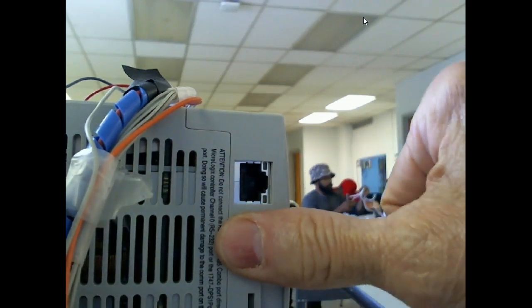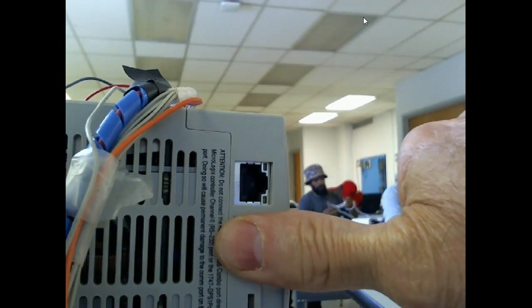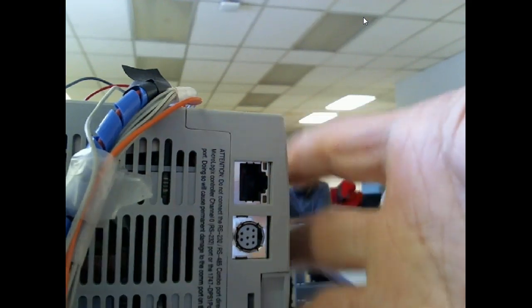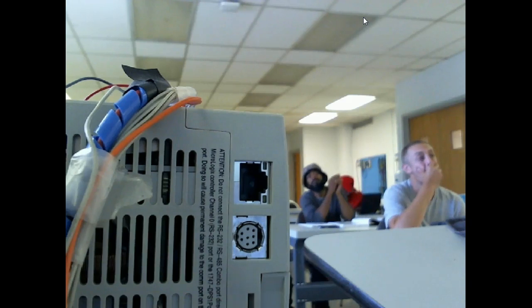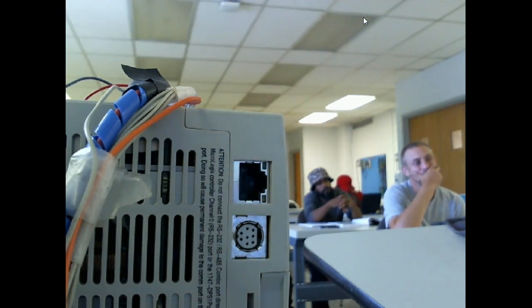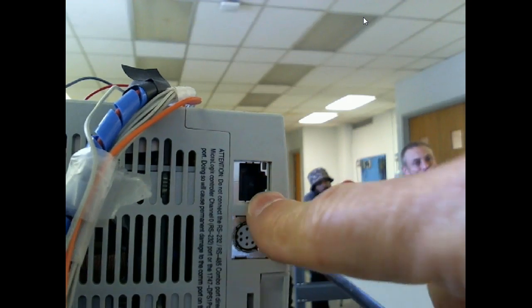Just about all your PLCs now, this is what you get. All your next version of Allen Bradley's use what we call Compact Logix. These are called MicroLogix. The Compact Logix use Ethernet, what they call Ethernet IP. Siemens calls it Profinet. So if you're out in the Siemens industry and you hear the term Profinet, Allen Bradley calls it Ethernet IP, and Siemens calls it Profinet. They're the same thing, uses RJ45.